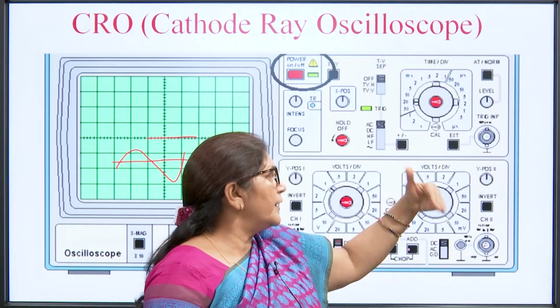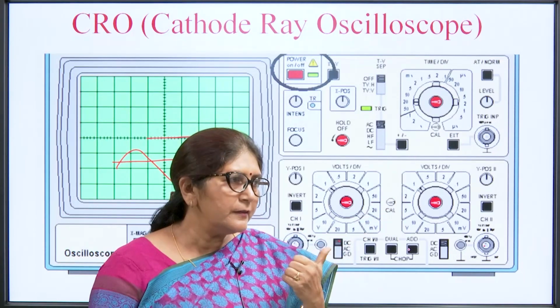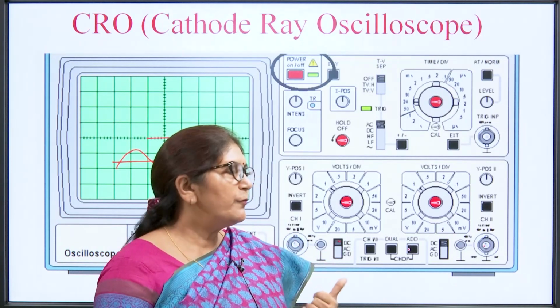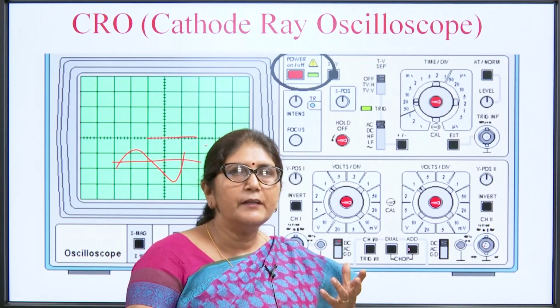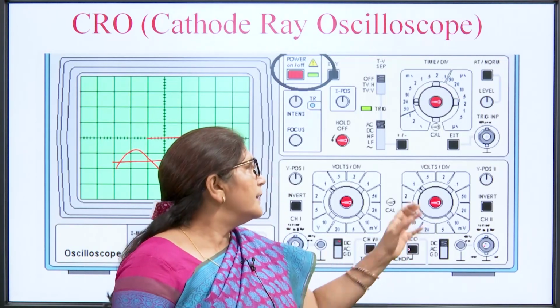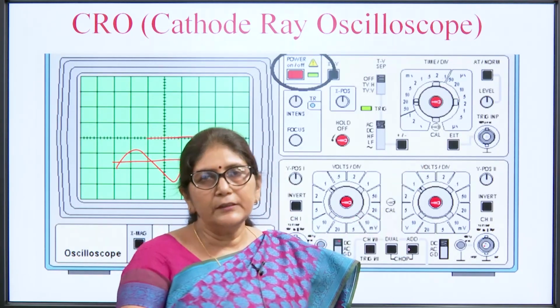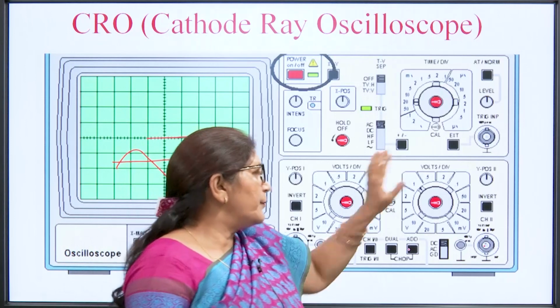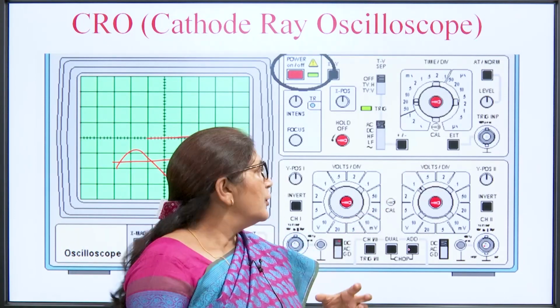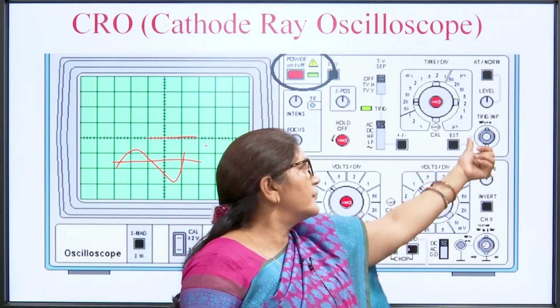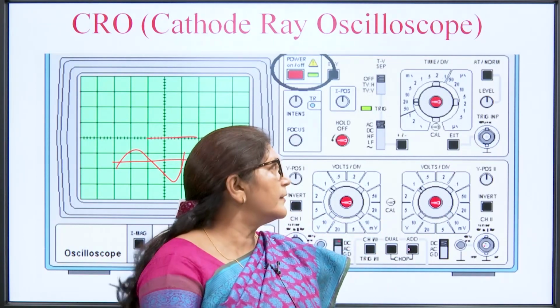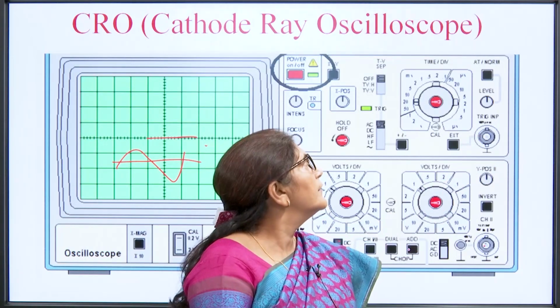This switch is out when we apply the internal synchronous signal, and if we want to apply the time base signal, a trigger signal, externally, then we will put it at the external position and press it, and then we will connect the external triggering circuit at this position.